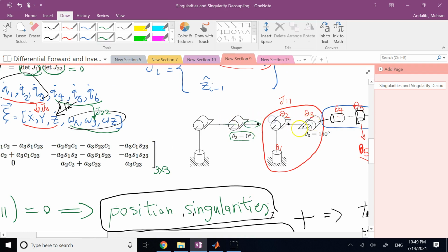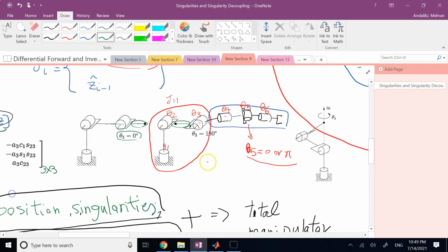or completely retracted back. And there is one other case here, and that is, if you remember, we talked about this, that your theta 1 can be arbitrary, but your theta 2 and 3 are such that your wrist point falls onto the original z-axis.